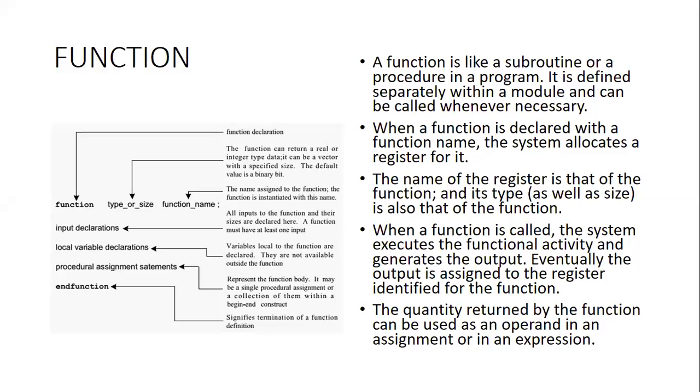Welcome everyone. In this session, we are going to see what a function is and how to adopt functions for Verilog modeling style. A function is like a subroutine or a procedure in a program. It is defined separately within the main module, not after the end module. It should be defined before the end module, but anywhere in the main module. And once you write the function, you can call it whenever necessary.